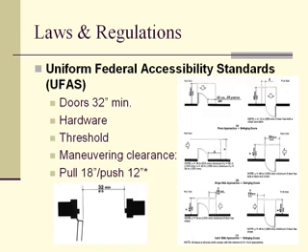Okay. Another important element is doors. We'll see that the specific requirement under the UFAS for doors is that they have a 32-inch clear minimum width, and that is measured from the stop to the edge of the door. So it is a clear dimension. Many times an architect or a contractor will spec out a 32-inch door, and will not provide a 32-inch clearance because of the door jamb and the door width and all that. So you have to start with 34 inches or more, or 36 inches to have that 32-inch clear minimum width.